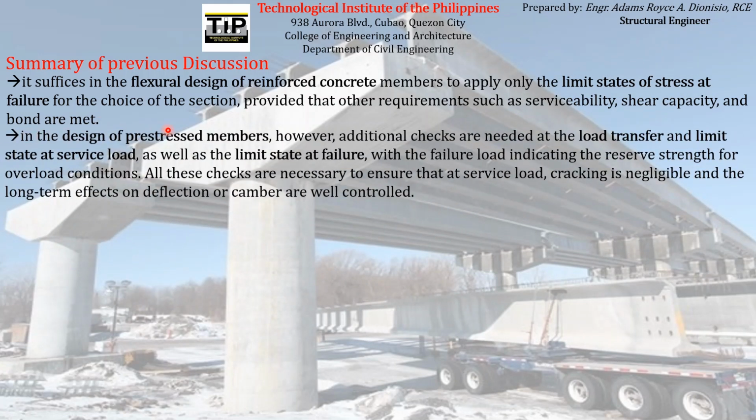But in the design of pre-stressed members, however, additional checks are needed at the load transfer and limit state at service load, as well as the limit state at failure, with the failure load indicating the reserve strength for overload conditions. All these checks are necessary to ensure that at service load, cracking is negligible and the long-term effects on deflection or camber are well controlled.